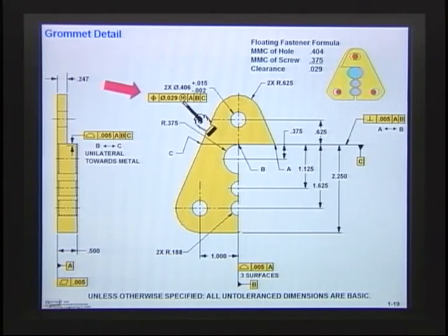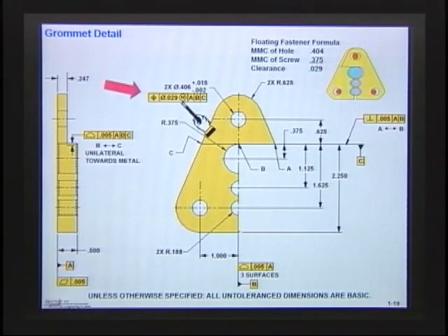Also, I put maximum material condition in here, and maximum material condition, you know what that allows? It says that as these holes get larger in size, you can be off position a little bit more. And I thought that was fine. The holes don't locate it. What you do is you take these 2 parts and you push them together, and once they're put together, then you tighten up the bolt, and it clamps the part down. So it's just a clamping force of the bolt against the face that holds the parts together, right? So if the holes were a little larger, the faces is what really holds the parts together. So that's why I thought that I could use maximum material in there.